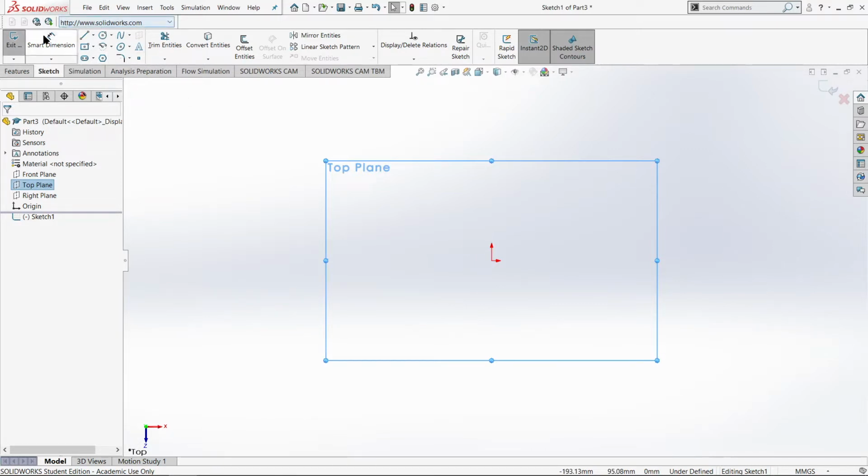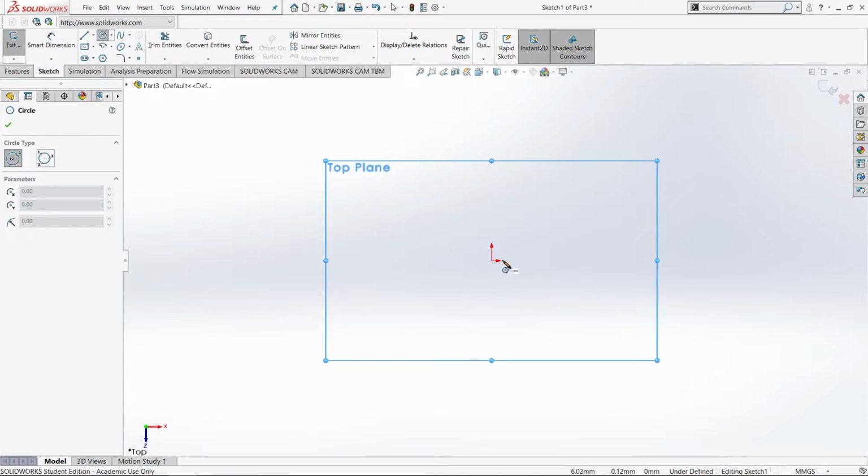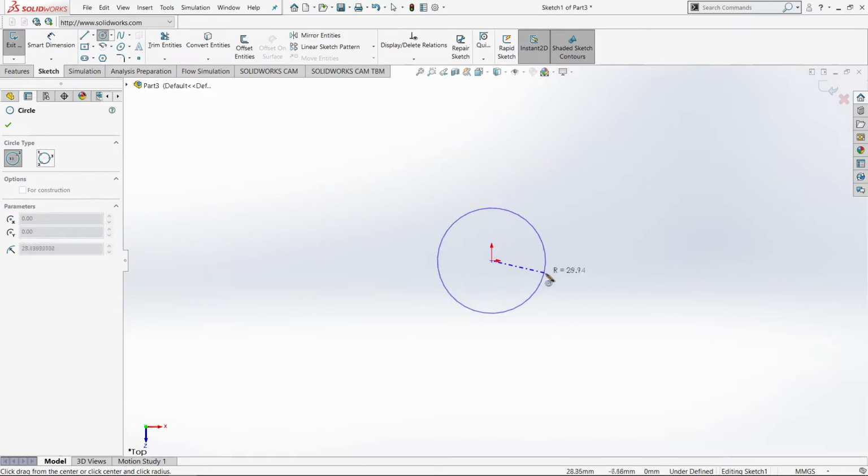We'll get started with the center circle tool. There's the center circle tool, there's a line tool, and there's the center rectangle tool. These 3 tools are the most used tools that I use. There's also a whole bunch of other tools at our disposal, but we'll just stick with the 3 most used ones for my use case. So we'll start off with the center circle. You click on the center circle tool and then you decide where you want the center point to be. We will make it the origin point, just to make things simple, and then you drag out and you choose how big you want your radius to be.